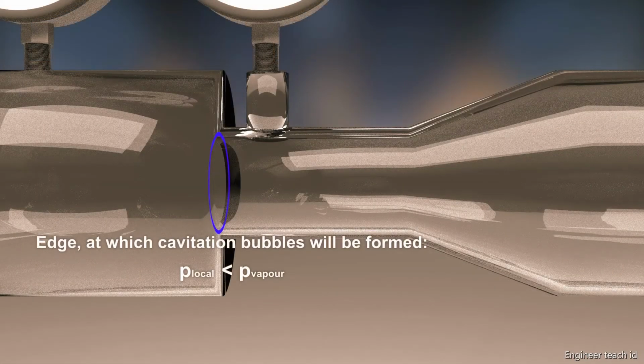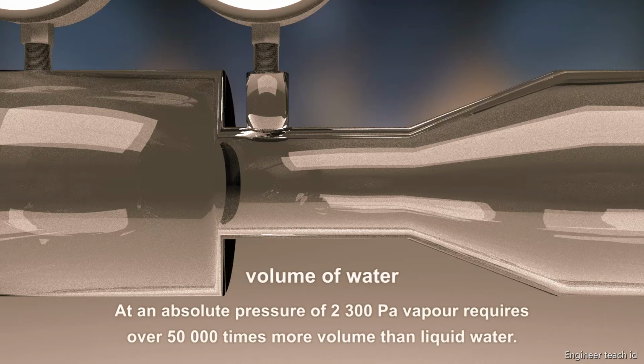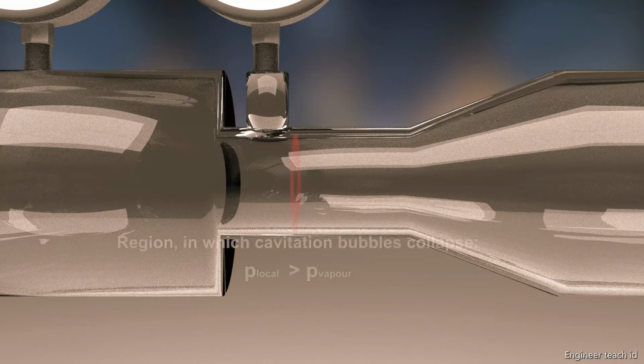The low pressure at the exposed edge causes cavitation bubbles to form. At a pressure of 2300 Pascal, a certain mass of water vapor requires over 50,000 times more volume than in its liquid state. The bubbles collapse as soon as they reach a region with a pressure above the vapor pressure.